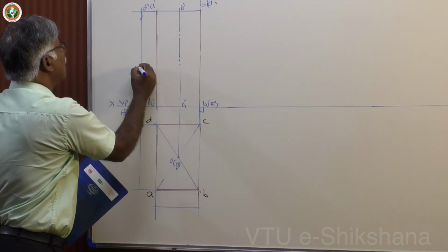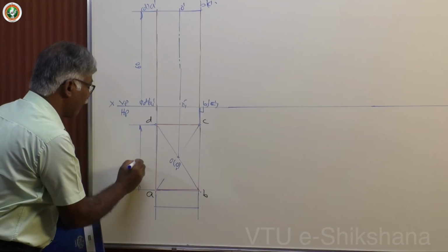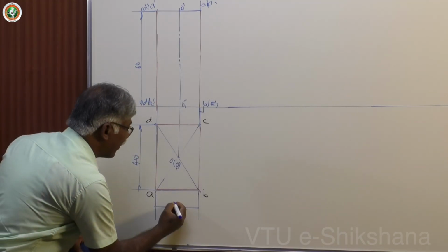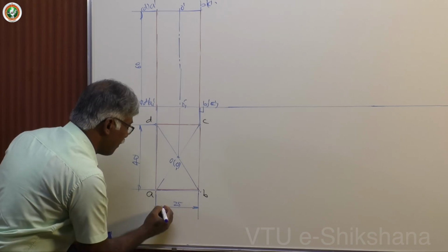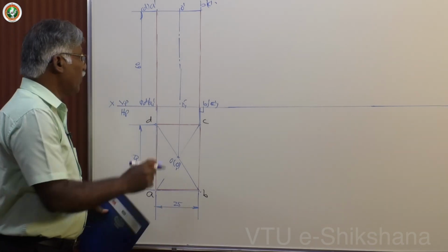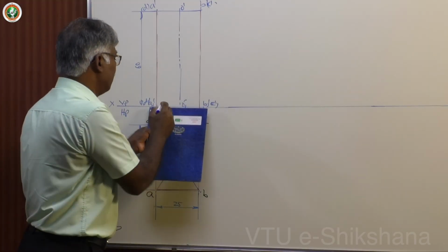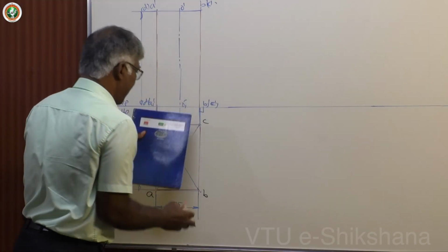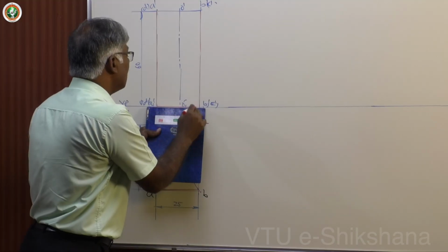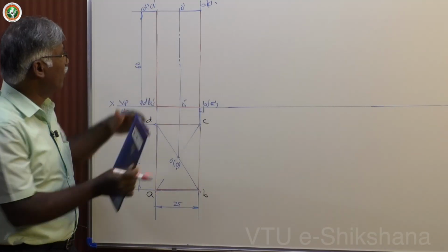This is 60, this one is 40, this is 25. So this is first position, top. Now just observe, I have left this. This must be in dark line. Normally we miss this line. Yes, this is base projection, this top face projection.